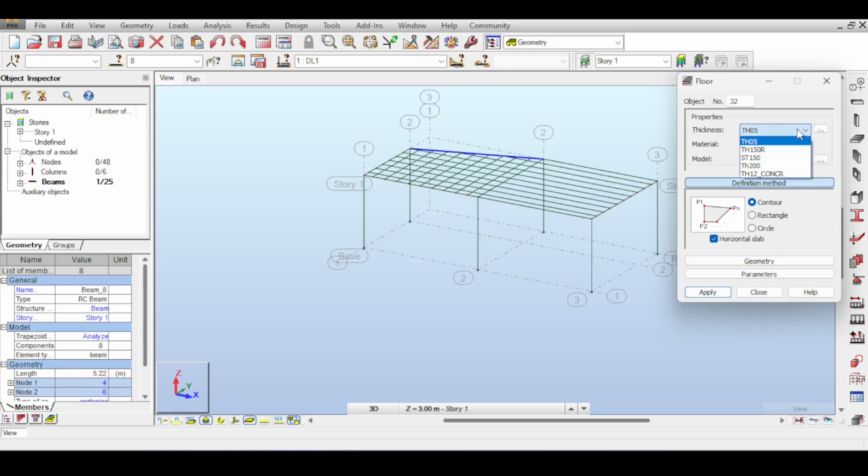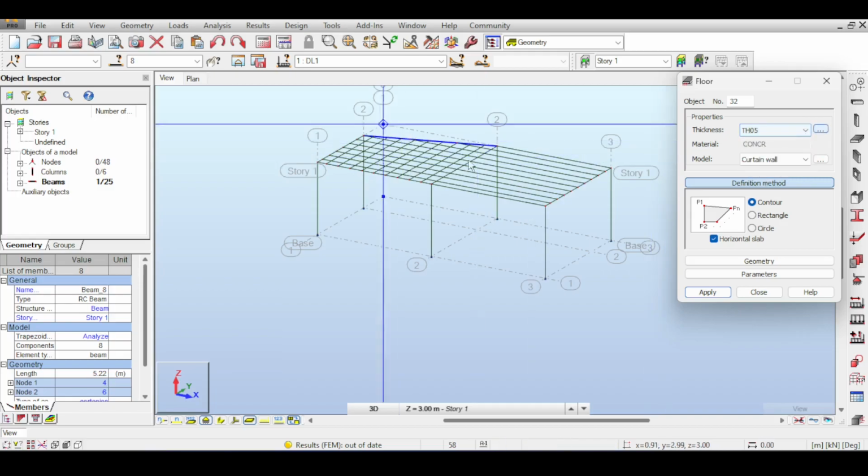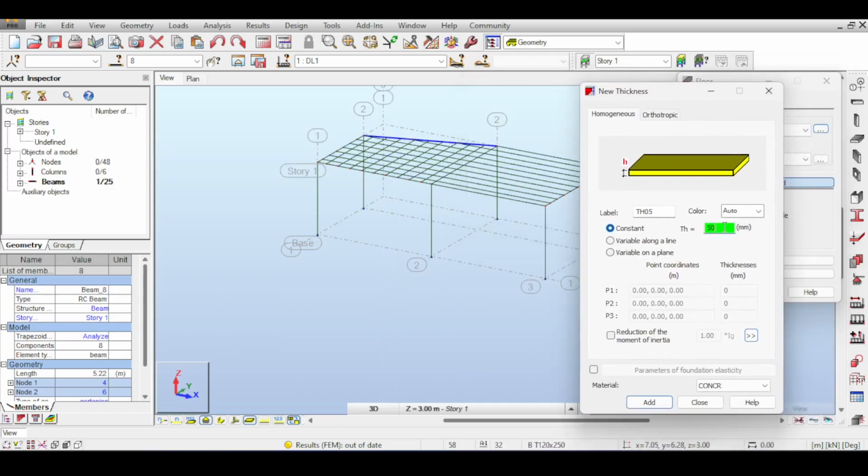But the actual more accurate way is to put a thickness close to zero slab. So although I'm a cladding fan, I'm just going to do this here. You can try the cladding at home and tell me if there are differences. There will be differences, of course. I'll put a 1 millimeter thickness slab. I will say here dummy slab.